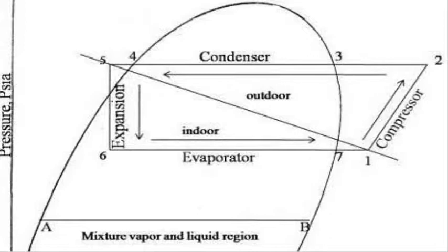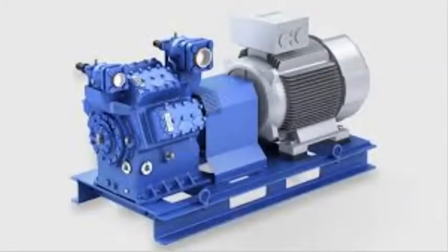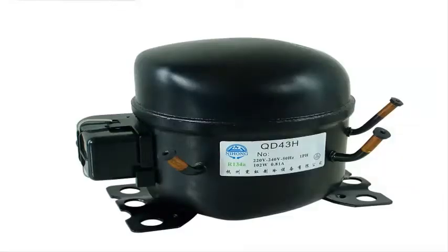Air conditioning theory. There are two laws that are significant to understand the basic refrigeration cycle and air conditioning. Thermodynamics' first law explains that energy can neither be created nor destroyed, but can be changed from one form to another. Thermodynamics' second law can help us better understand how the basic refrigeration cycle works. It states that heat always flows from a material at a high temperature to a material at a low temperature.